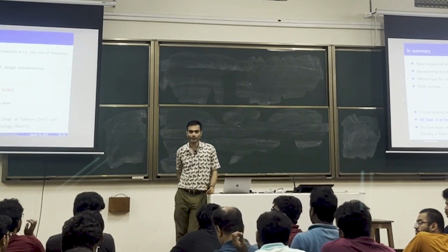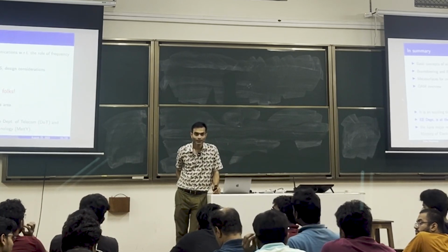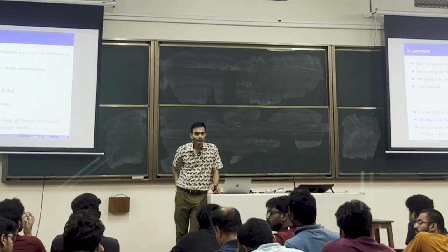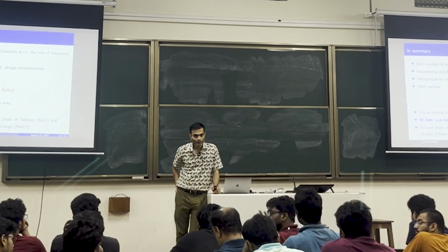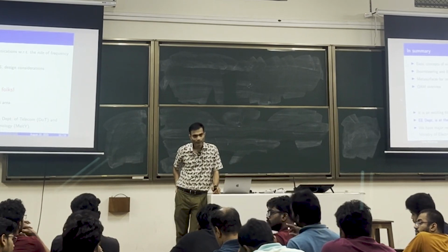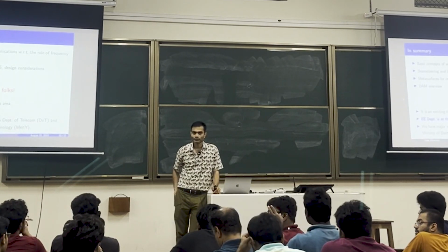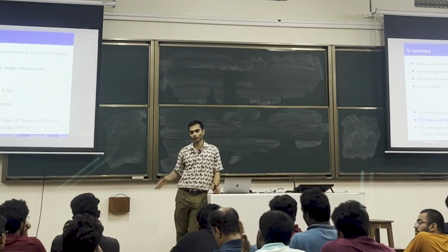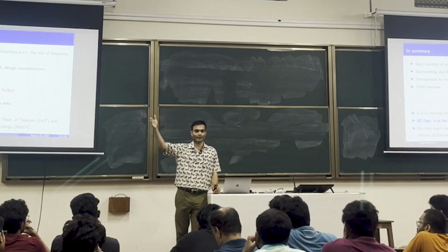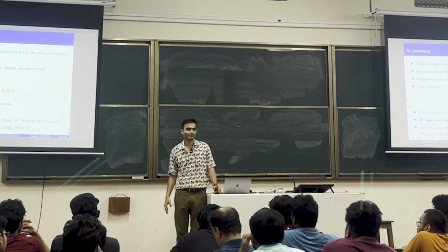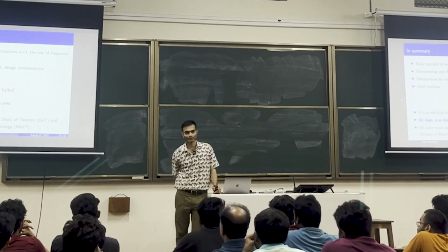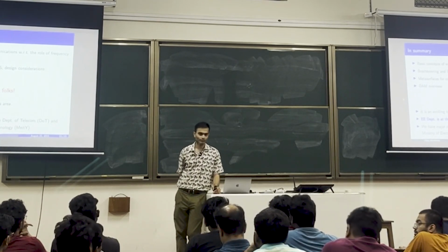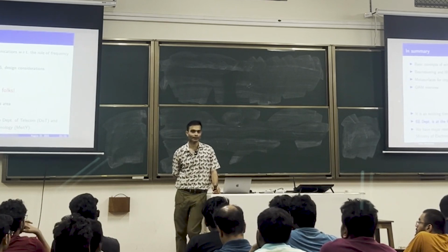It will be a finite surface area. Assume an incoming wave is coming. The IRS is reflecting at theta 1, and the remaining area surrounding the IRS will be reflecting at theta 2. Correct. So both waves will be present at the receiver point, with different reflection coefficients. If my building has a poor reflection coefficient, it will not reflect so much. I have to take care of all of that, because both are at the same frequency. So stray reflections have to be taken care of.